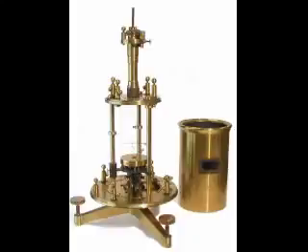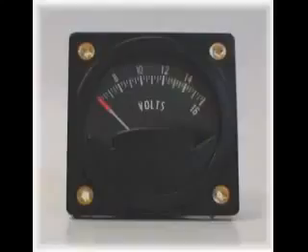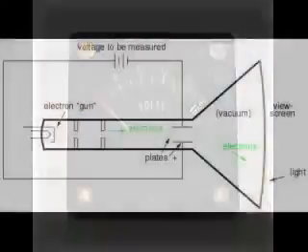One great advantage of the electrostatic meter movement, however, is the fact that it has extremely high resistance, whereas electromagnetic movements, which depend on the flow of electrons through the wire to generate a magnetic field, are much lower in resistance. As we will see in greater detail to come, greater resistance, resulting in less current drawn from the circuit under test, makes for a better voltmeter.